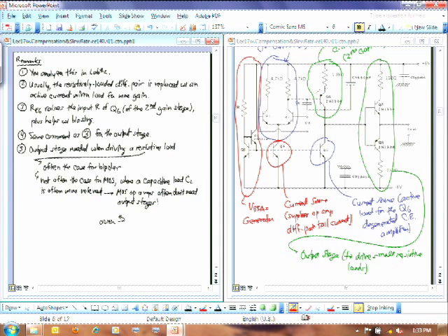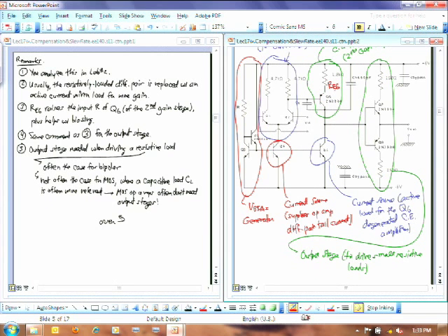Okay, that's part of it, yeah. But that's not entirely it. Larger swing is one, a larger range of inputs is what it does. A lot of good answers here. All these are valid answers. I was looking for it increases your input impedance for this, so it doesn't load this as much. But all your answers are just as good as mine. So part of it there is, it raises the input resistance of Q6, right?